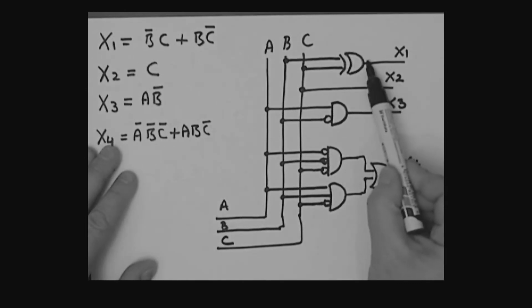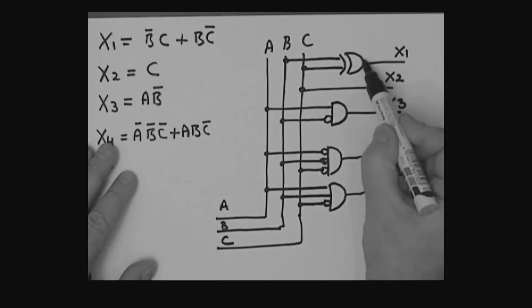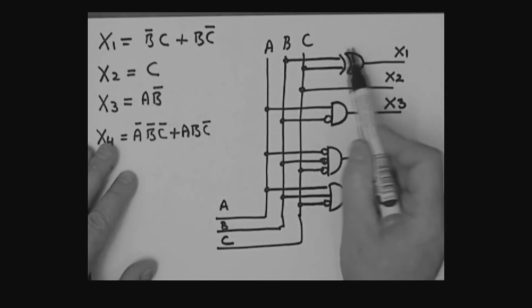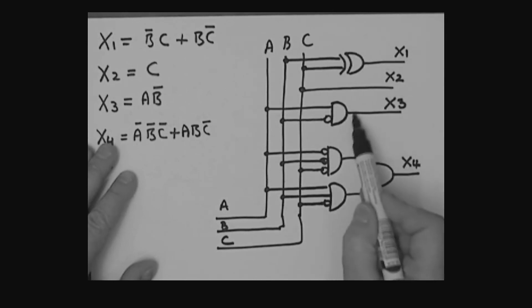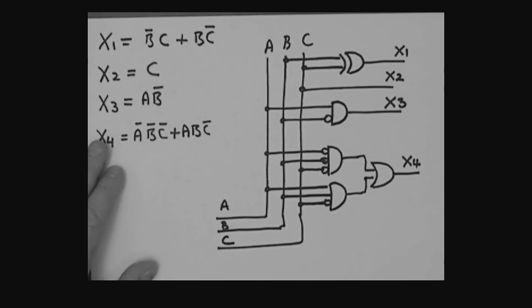Yeah, well, could you not put an inverter here, inverter here, inverter here? Okay, in other words, that would then produce a low acting output signal. So in a sense, it's like putting a bubble here, which would make that what? It would make that an exclusive NOR. If I put a bubble here, it basically makes that a NAND gate. And if I put a bubble here, that basically makes this thing over here a NOR gate. Okay? So it's very simple, really, to deal with that issue.